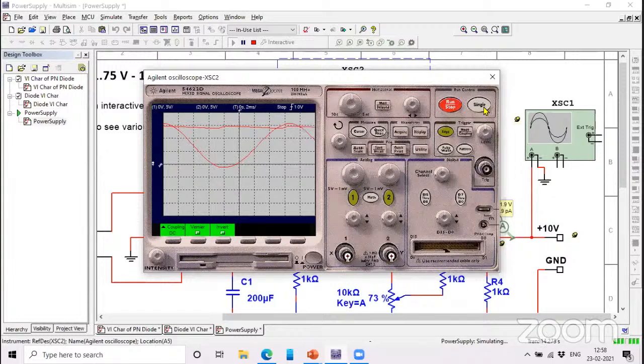Now if we click on channel 2, we can see the rectified filtered output signal. Okay, we take a single value and we can measure it using the cursor. So we move along the y-axis using this terminal. We move along the x-axis by clicking over here. It will need practice. So if you practice a lot, then you can easily do any experiments.